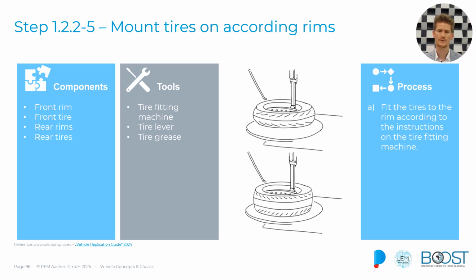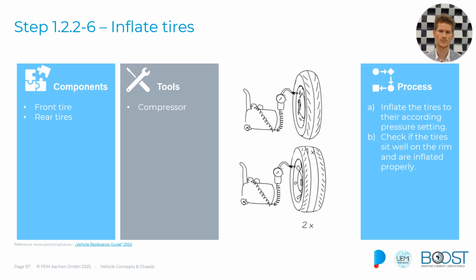The next step would then be to inflate the tires. Make sure again to check which kind of load the tires would take and which are the corresponding pressures the tires would need. High tire pressures usually help you cope with high loads. The lower the tire pressure is, the smoother the ride will be, but also the wear of the tire will be bigger. So this is something where you have to find the best compromise for your clients at this point.